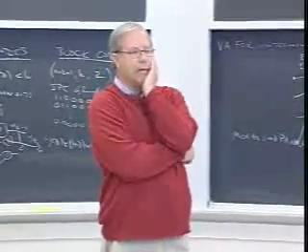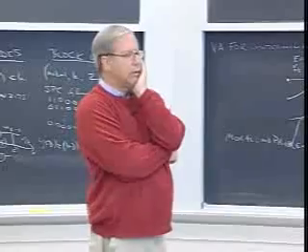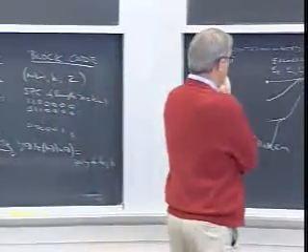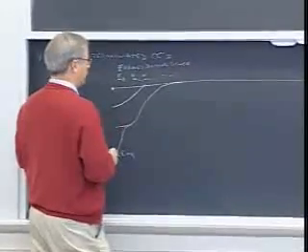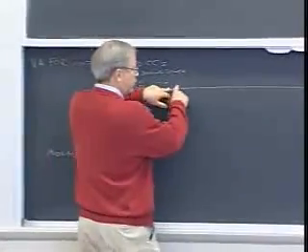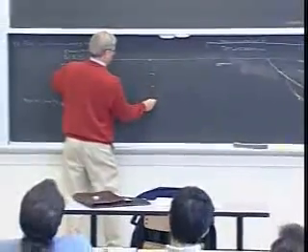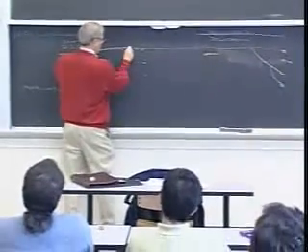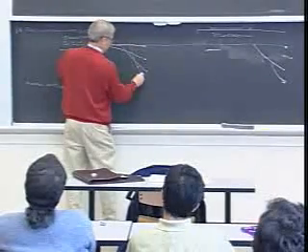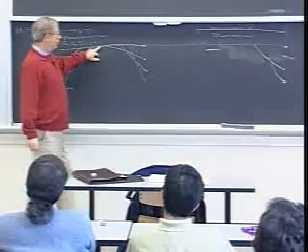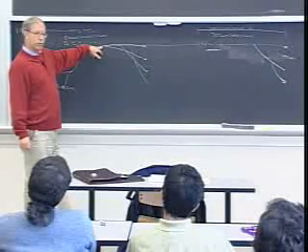Yeah? Just choose the best path at the point of synchronization? At this point? Well, notice that we don't know that we've synchronized until we've continued further, and where we've really synchronized is when we see that every survivor path has a common root. At that point, there is really only one path here.